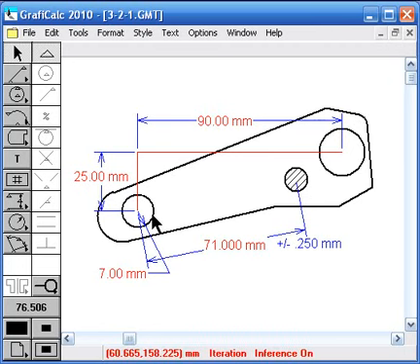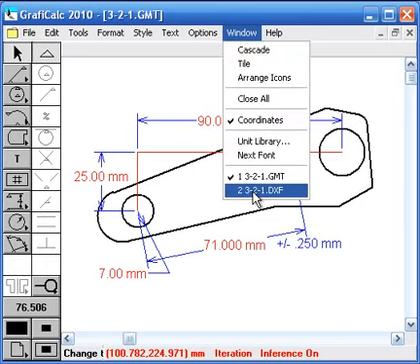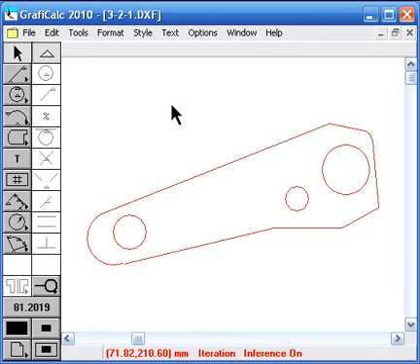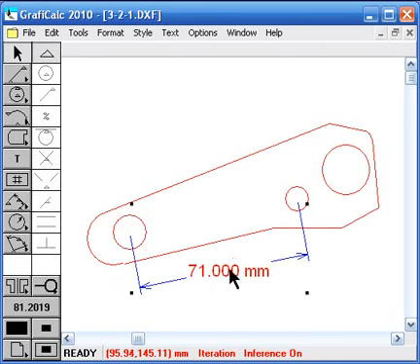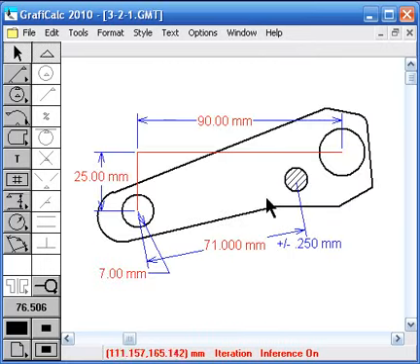And so the manufacturing engineer knows that he can hold this center of this true, but then this will have a tolerance. So what the manufacturing engineer can do is, supposing he got this as a CAD drawing in any CAD application, he saves the geometry in the DXF format, and then he reads in the DXF file here. So this is the critical dimension that he needs to satisfy, which has got a tolerance allocated of plus minus 0.25.